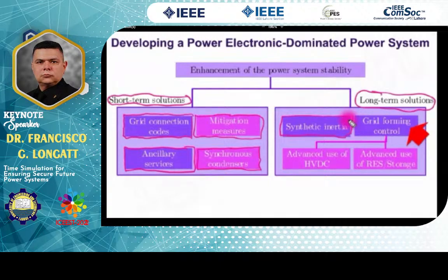However, there are two very important characteristics that I would like to say regarding grid forming. The first one is that the model of the grid forming control can be in a circuit that is basically a voltage behind impedance. For that reason, this model is more replicating the behavior of that real synchronous machine.